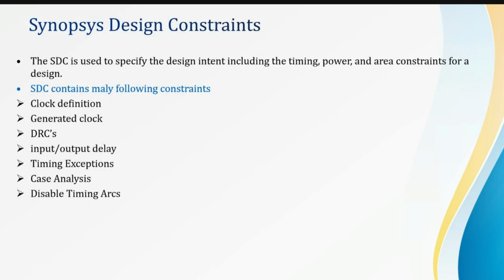Next will be the SDC. SDC is nothing but the Synopsys Design Constraints. In the SDC, it will contain the information of the clocks, your DRVs, that is the input transition, capacitance, output load, what will be the input delay, output delay, your setup time, hold time, all the timing exceptions, all the timing related things like set_case_analysis, disable. Whatever it is doing, it is doing it on the Synopsys Design Constraints.